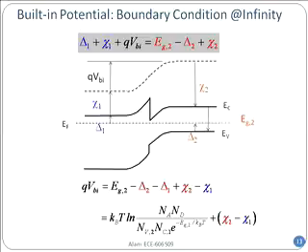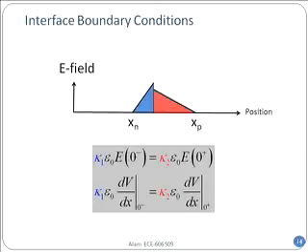And chi 1 and chi 2, of course, you read from your table or from a book for that material. This is tabulated. How do they get chi 1 and chi 2, by the way? These all come from the photoelectric experiment, you remember, which allows electrons to be pumped up into the free region so that they can be collected. So that's from the first part of the course. Okay, so you know QVBI. If you know QVBI, then the rest of the things are easy.